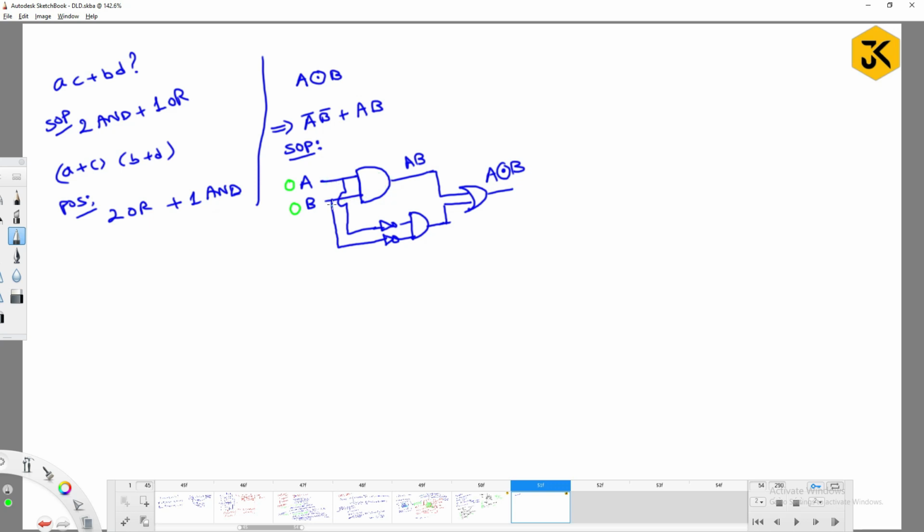So try to observe, 0 and 0 you are going to get 0, as this is an AND operator, right? Now here you will get 1 and 1 because it is the complement, and 1 and 1 is 1. Now on the OR operation, 0 or 1 is 1, right? When you give 0 0 as input, you are going to get 1 as output. Similarly, if you take 1 1 as input, you are going to get 1 as output. Try to substitute and solve it. If you give 0 1 or 1 0, you are going to get 0, because this is the property or truth table of the XNOR gate. For that, the expression is like this, right?